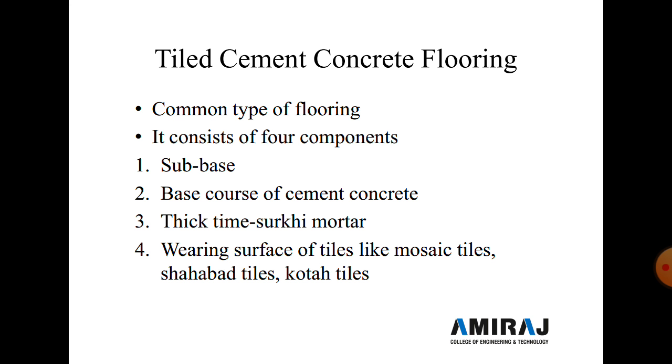When the base course cement concrete has hardened, its surface is cleaned by a stiff broom, and it is wetted the previous night and excessive water is drained. Now third point is the thick lime surkhi mortar.